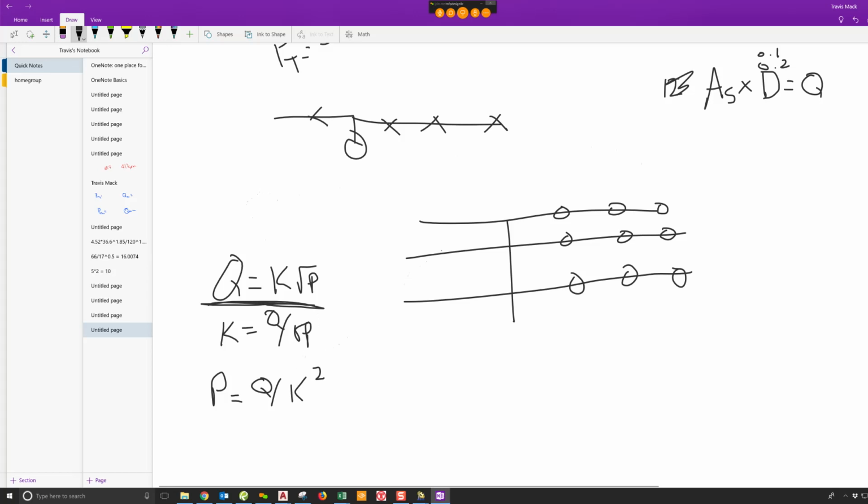Oftentimes it depends on what calc program you're using. I hope most of you are on AutoSprink, and for those of you that aren't, I feel sorry for you. But if you ever have to figure out the minimum pressure at a sprinkler, let's say we've got this sprinkler right here. We'll assume this is a warehouse, a simple tree. We'll say our sprinklers are spaced at 120 square feet and the density is 0.2. So these sprinklers all have 24 gallons per minute. That's just 120 times 0.2 GPM, and I apologize for how bad I write with the mouse.